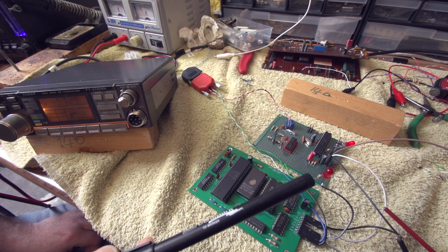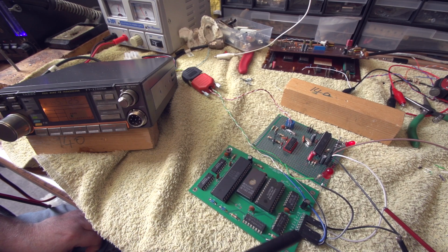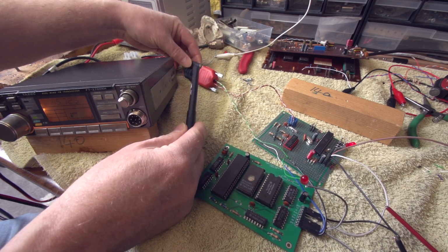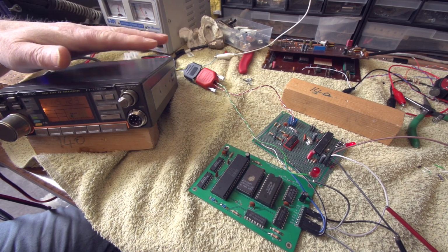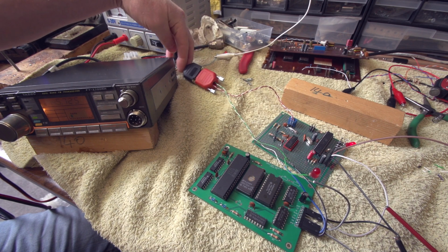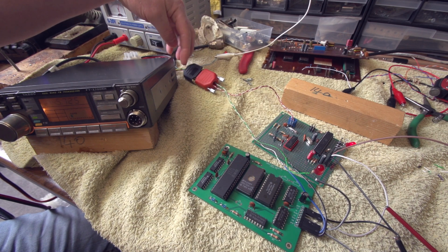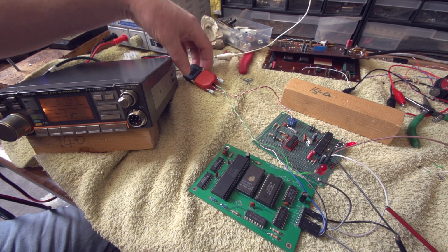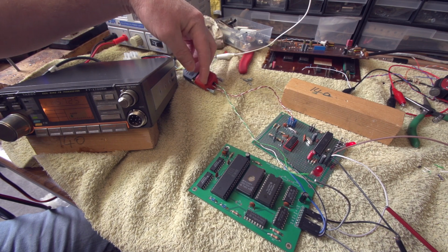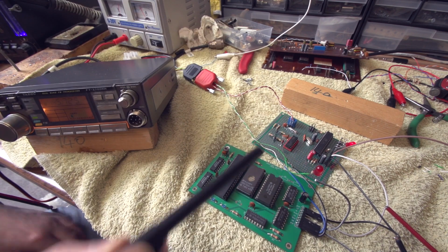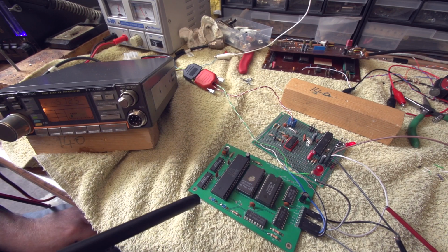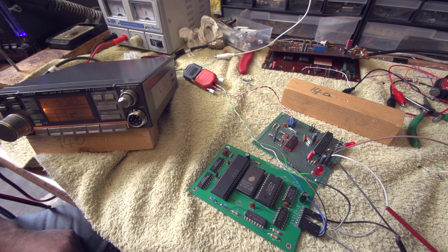This LED here is showing the CW ident coming out of the card. You'll notice I've got a little connector thing going on here. That's wired from the back of the radio, because the radio's been slightly modified to give me these signals. So we've got discriminator output from the back of the radio here, and also squelch line or busy line. That comes to this connector, which means we can extend this easily with a normal cable, and that can then connect through to the audio card when it's complete. So that's as far as we've got, and I'll show you what happens when we inject a signal.